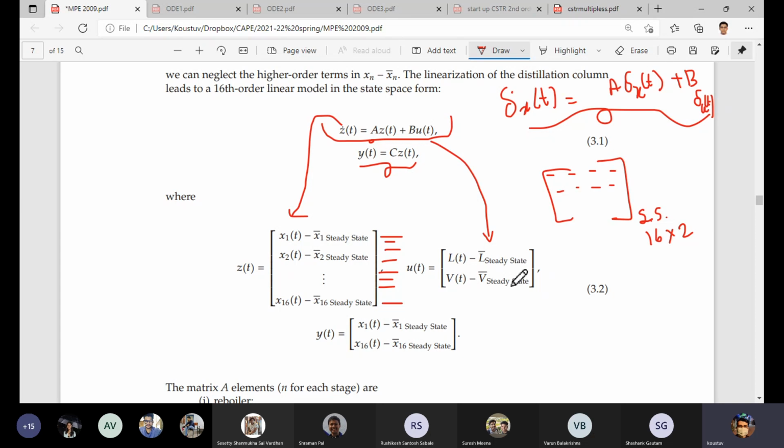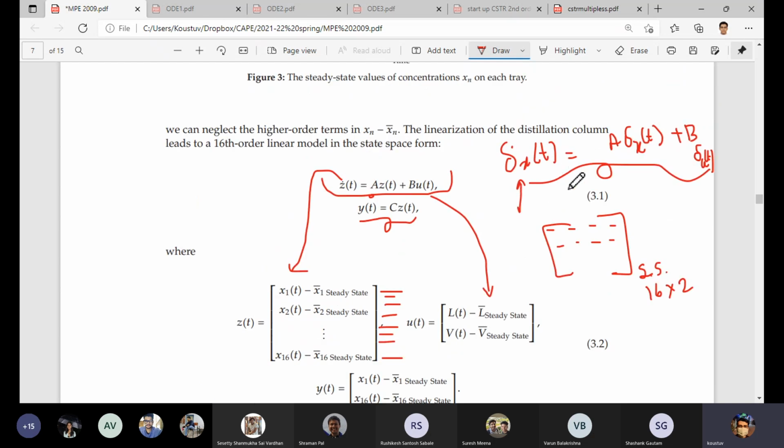Another important point I would like to make is that the concept of this linearization is basically required. The deviation variable perturbation, this delta amount, and their time varying features or transient behavior is actually nothing but the input to the controller.